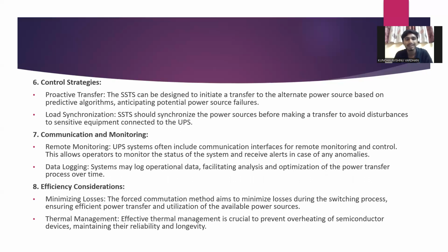Control strategies. Proactive transfer, load synchronization. The SSTS can be designed to initiate a transfer to the alternate power source based on predictive algorithms anticipating potential power source failure. SSTS should synchronize the power sources before making a transfer to avoid disturbances to sensitive equipment connected to the UPS.